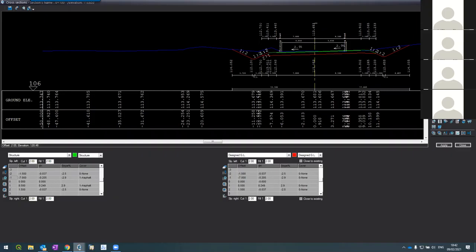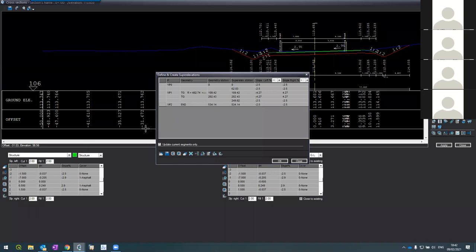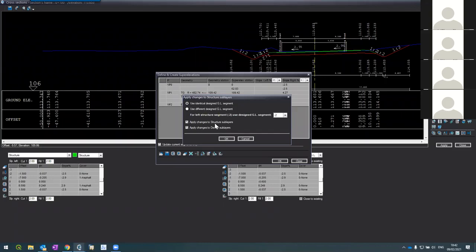Now I want to choose the slope. In the super elevation window, I want to choose slope percentage. Since I break it into 2, like minus in your example, I break to -1 and -2. And here now, I need to choose the 2. What you do, you first of all define here, then you copy, you change to -2. And actually, you don't even need to copy.